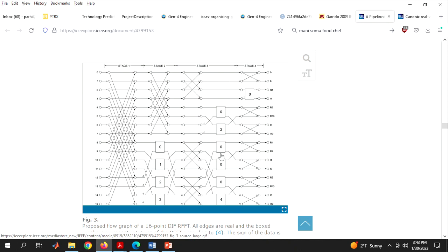These numbers are the twiddle factors. So again, we have now replaced all these half butterflies, complex to real. This is just concatenation, and then 1 complex became 2 real and 2 complex became 4 real. And so this is the FFT structure that is optimized for real signals, without the need to compute an 8-point complex FFT and then go through a very complex post-processing step.